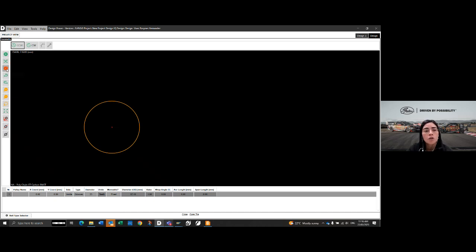You have an option to delete a pulley if you don't need it, an undo option, and options to zoom in and zoom out, which is really useful depending on how complicated your drive design is. You also have zoom fit, which is really nice as well, and I'll show you later how to use it. You have an option to pan, and options for pivots or slotted idlers, which I'll show you in a minute.